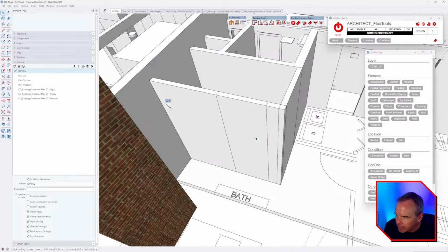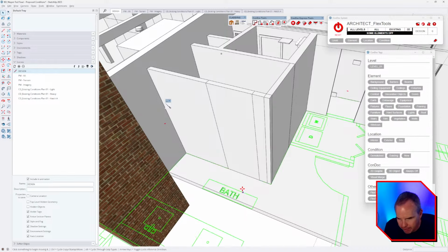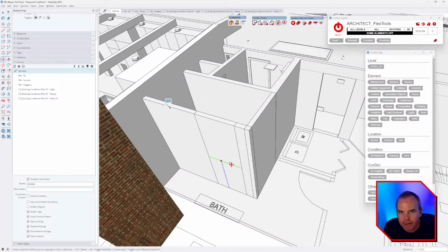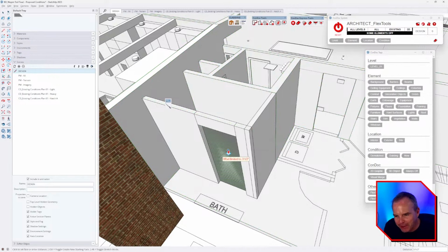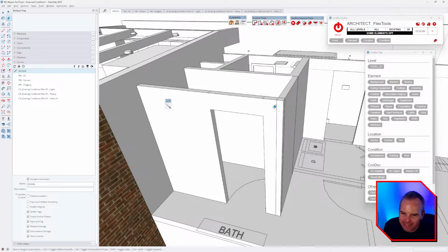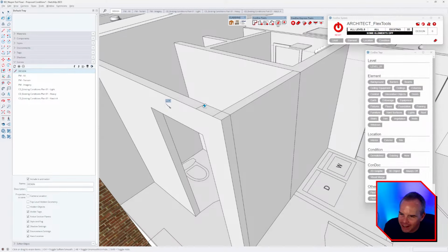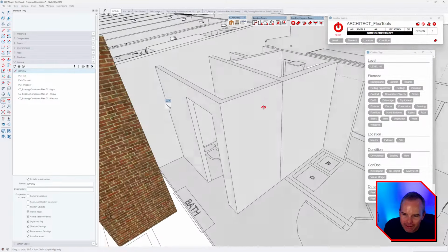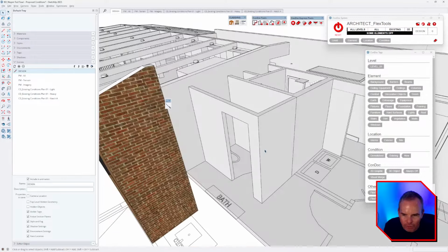So let's see. All right, and then I could make a copy of this edge straight up like that, and I'm going to snap it here. I know, John, we did a whole presentation on that, didn't we? Talking about the right way to build these things. But no, that's definitely burned into my head now. The main thing is it's either 3.5 on the inside or 6 inches on the exterior walls, because you're going to dimension to the exterior face of the sheathing. So that works for me.